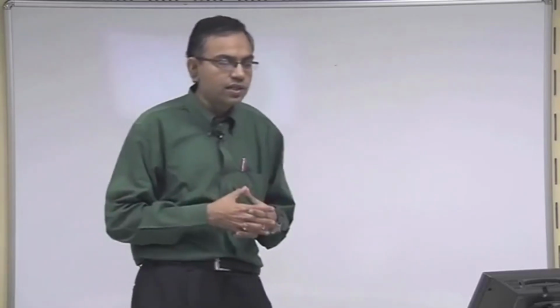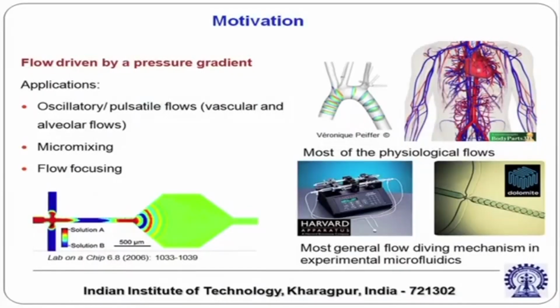Then you can have various technologies in which you can achieve microfluidic mixing. For example, one of the possibilities is that you introduce two fluids by a driving pressure gradient and allow the fluids to mix by stretching and folding of the fluid elements as the fluid passes through an undulated passage or a corrugated passage.